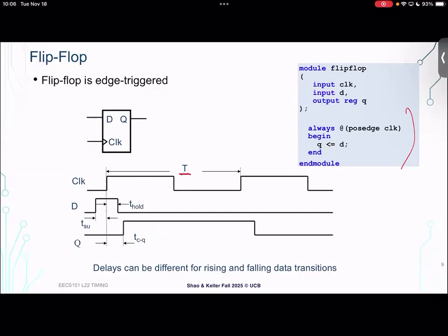We're going to define those now. Just to be crystal clear, the clock pin is what triggers the flip-flop to pass data from D to Q. If we're not at the rising edge of the clock, then the flop is going to retain its previous value and send that to the output Q. So that's the behavior functionality. We're all familiar with this.